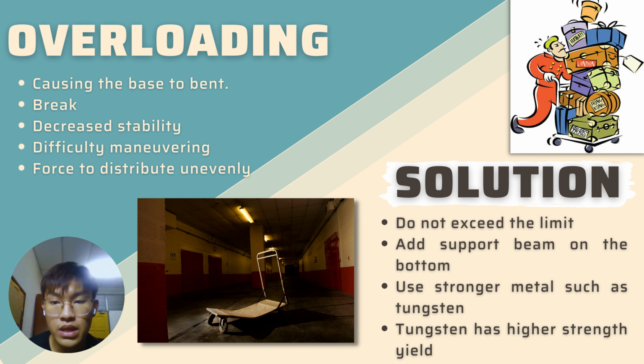As you can see, when the base is bent in the middle as the picture shown in the bottom left, the surface becomes slanted to the middle, which will cause the loads to be slanted to the middle too. This will cause the force to distribute unevenly, with the force focusing more on the middle instead of the front and the back of the truck.